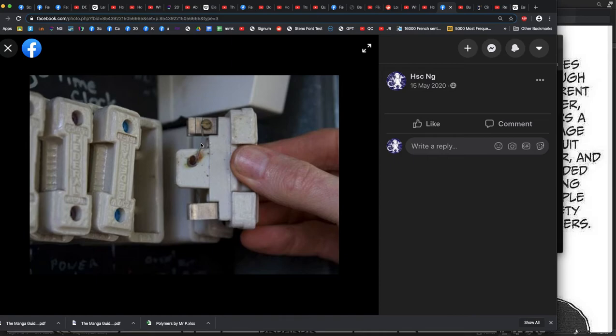This kills people, particularly electricians. What people would do is replace the fuse wire with a piece of copper wire. And obviously the copper wire is not going to melt, right? So effectively they're just bypassing the fuse. There is no fuse, so there's no current protection, nothing limiting the current in your house. It starts fires and it electrocutes people.